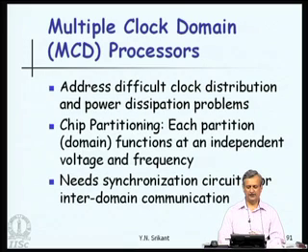So, it is well known that in a large CPU or large chip in general, supplying the same clock to all parts of the CPU is very difficult, it is not easy. It is simpler if separate clocks are used in different parts of the CPU, but then clock synchronization between these is a very difficult problem. So, it is not easy to use such processors.